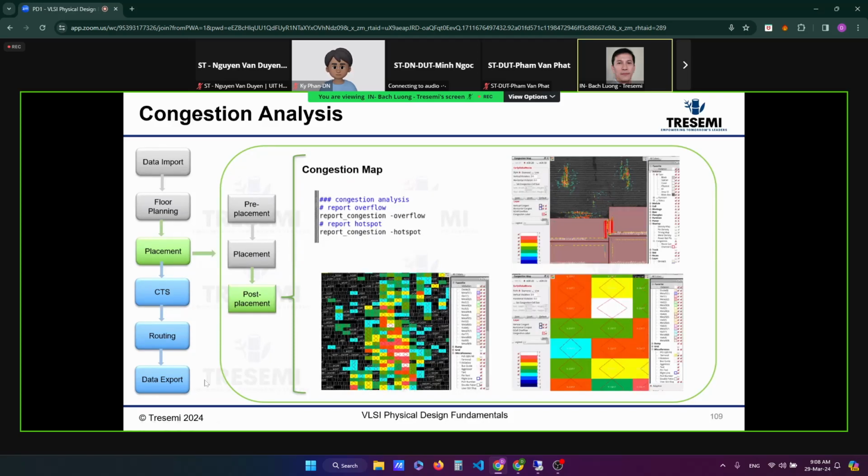Okay, so the congestion map is the way the tool lets you know which area has congestion. By looking at a congestion map, you know where congestion is and where to resolve it. So here's just an example. This area here lights up. This is the legend, meaning this is severity: 0, 1, 2, 3. So there's 7 tracks over. Basically, what it means is this red is short of 6 tracks. So you can see this area is congested here, and on this side. You can change the color if you want to, but these are just the default colors that showed up.